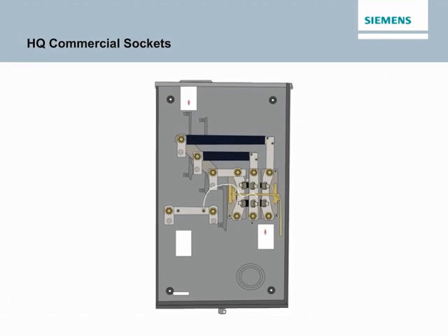A hub adapter plate, part number H9747-1113, is available to adapt an HD hub to an RX opening. HQ sockets are available with 4, 5, or 7 jaws. For 200 amp rated sockets, a 5th jaw can be installed at a 9 o'clock position in the field, but requires the user to run a wire to ground the jaw. The 5th terminal kit part number is H35815-2.